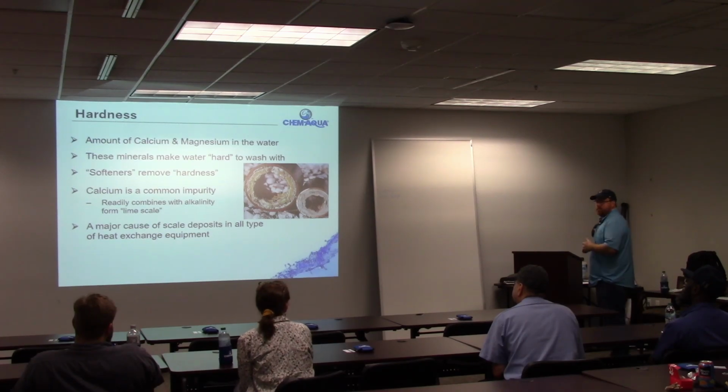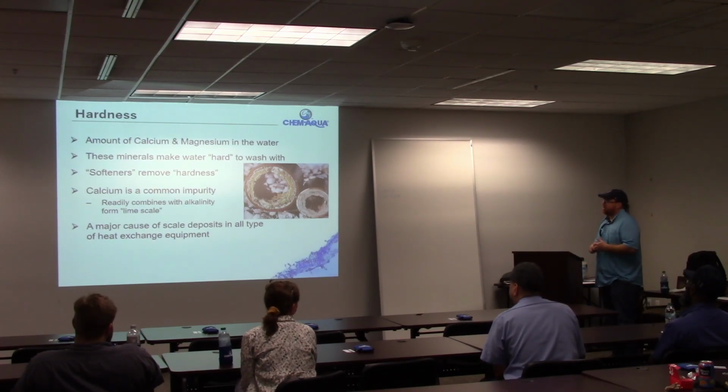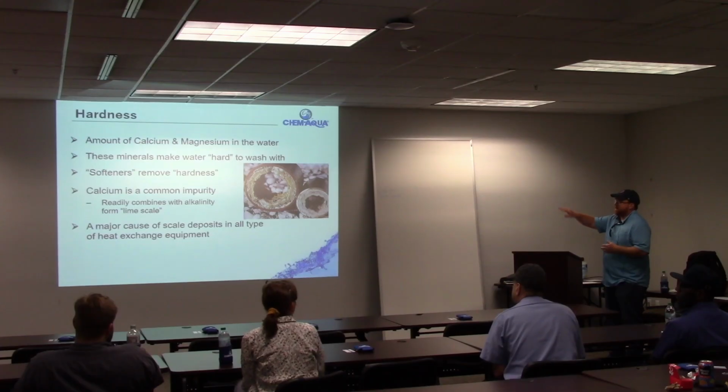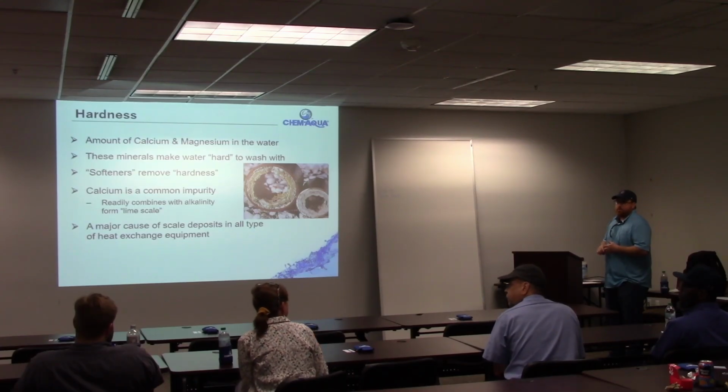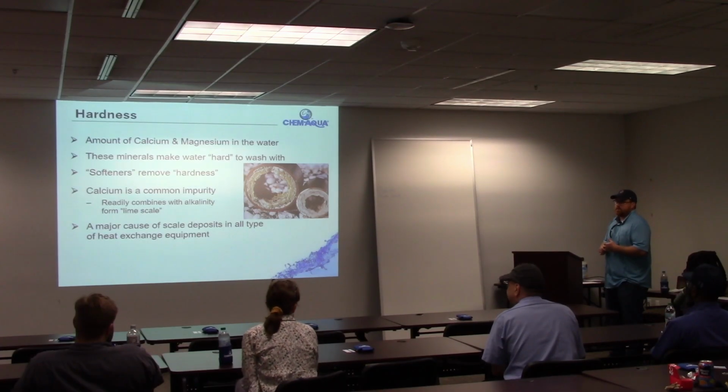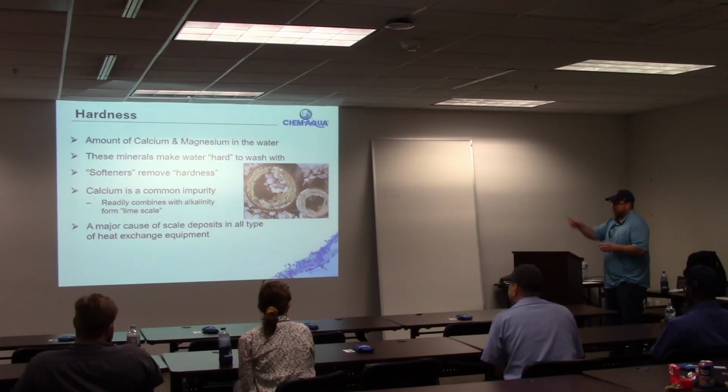Could you even run a chiller with that much scale? Probably not. It will probably shut off on high head pressure. Yeah. Once your approach gets to 5, then, yeah. I mean, your compressor has to work so hard at that point. Yeah, there's no check.